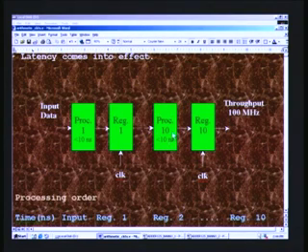Ultimately it is process 10 here, and you will notice that immediately after each process you have a register, clocked by the usual system clock. At the positive edge of the clock, whatever is available as the process 1 result, these being intermediate results, will be registered here. Whatever is registered here, with the arrival of the next clock, will go into process 2, where it will be computed, and when the second clock arrives it will be registered, and so on.